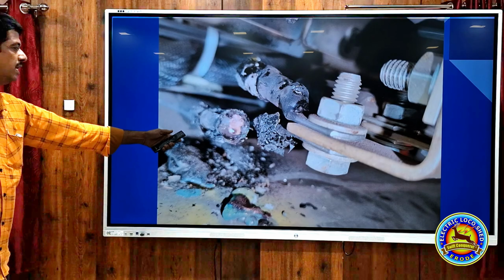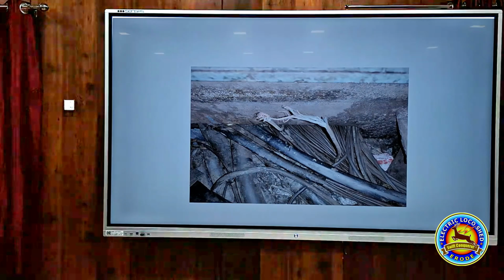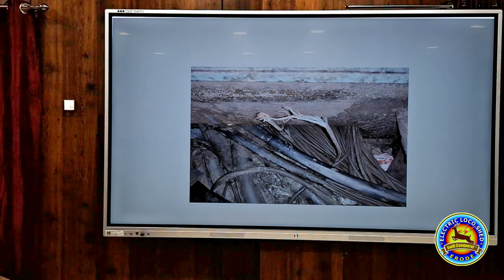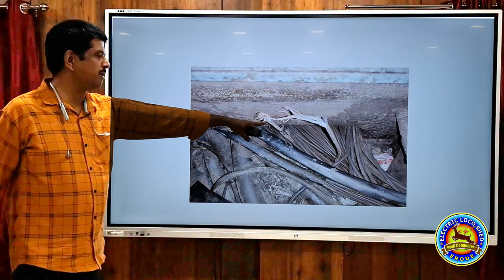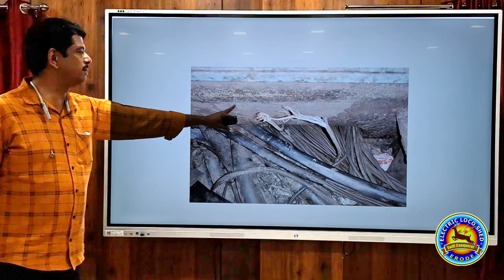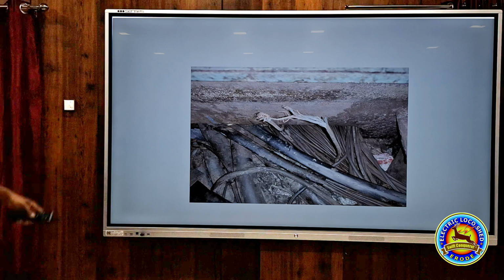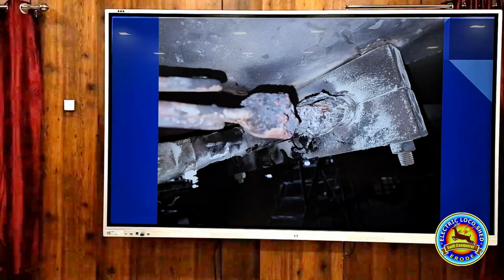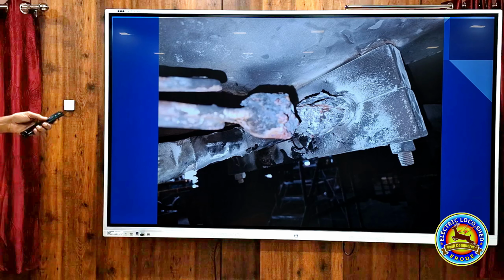This is another cable lug crimping failure which caused an open circuit. This is improper bunching inside the cable trench. So many cables were laid without proper bunching, which caused insulation failure. One cable was continuously rubbing in the cable trench, which caused insulation damage and later burnt in that cable trench. This is another cable junction which had a crimping problem which caused melting.